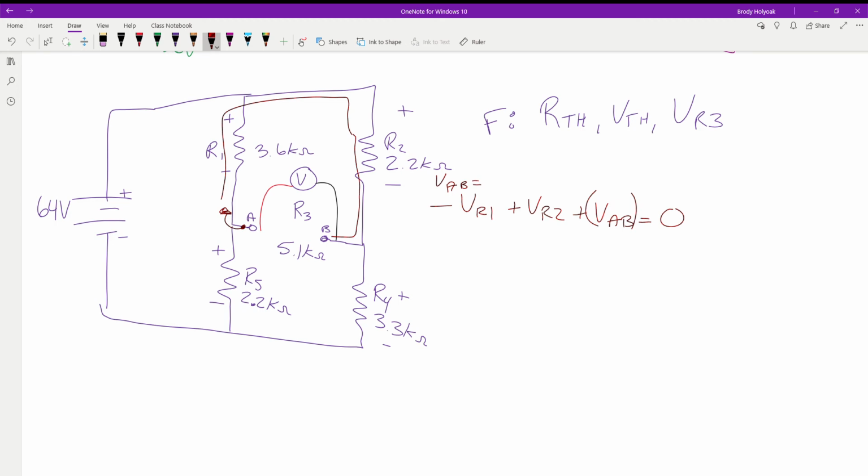So how do we find what these voltages are for this? Just voltage divider. Yeah. Well, they're not in series because you got to look at how they are in the total circuit. So each individual branch, so R1 we could find using voltage divider because what's in its series branch? R1 and R5. Because there's nothing connected here right now. So these two resistors are in parallel with our supply. So if those guys are in parallel supply with nothing else in here, it's just going to be the voltage divider between these two components.